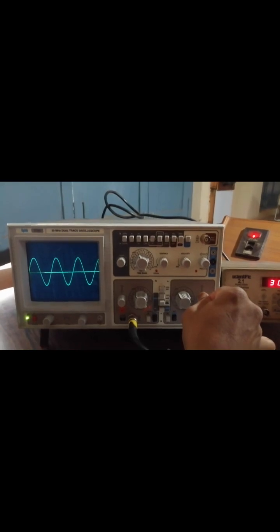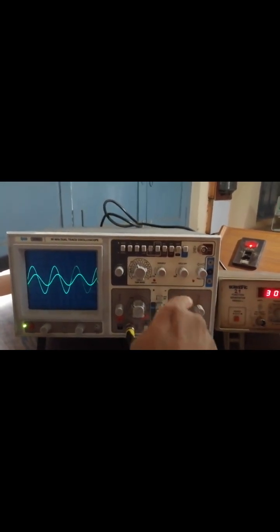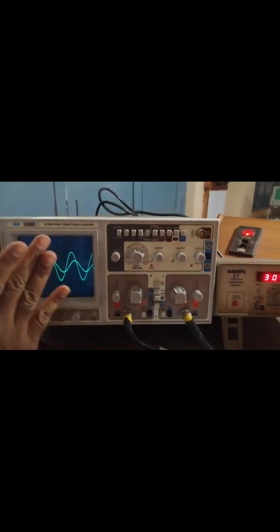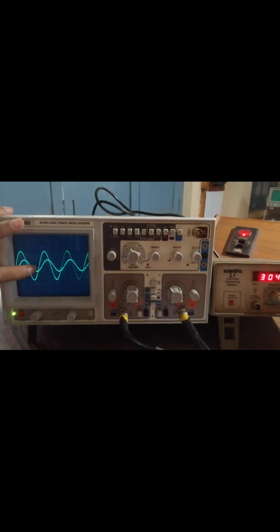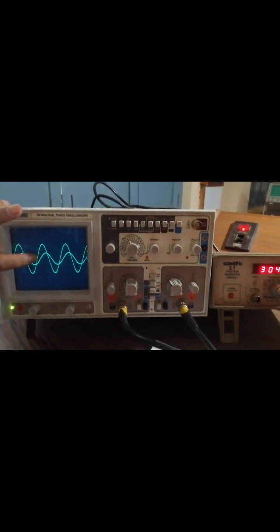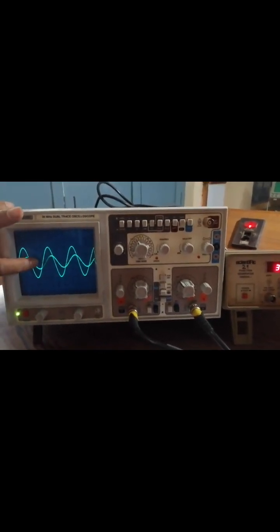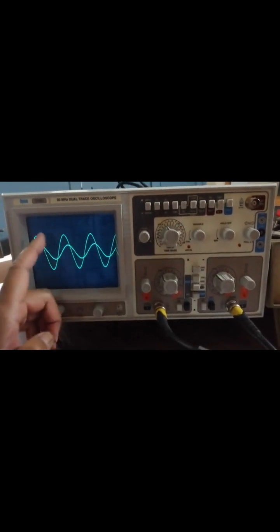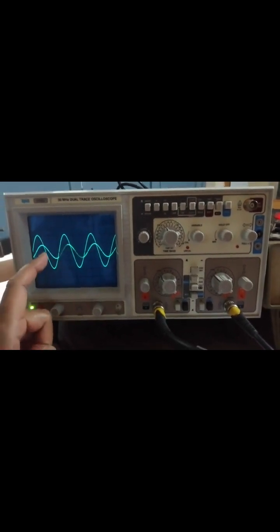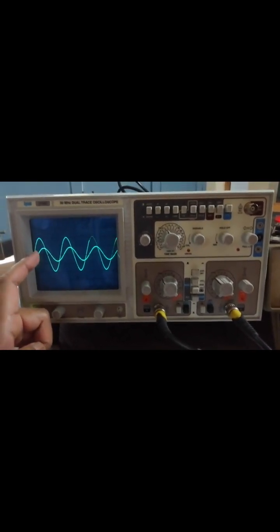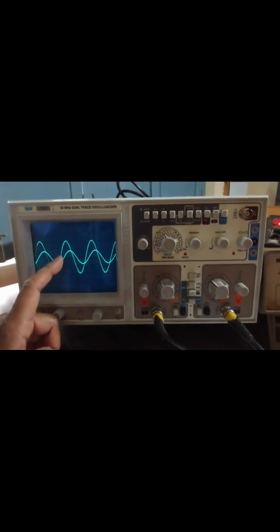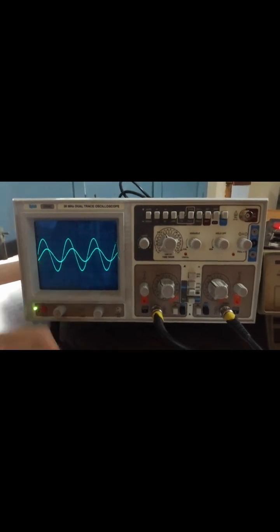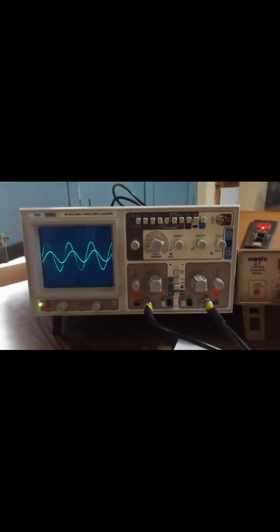I am activating the output channel and releasing the ground button. You are observing the output here. So it is basically a lag compensator. Lag means the starting point of the output should come after the starting point of the input. It is an indication that the output is lagging behind the input. So you need to consider the starting point, which comes first. Here input occurs first and then the output, so the output is lagging behind the input. In this context, we call this a lag compensator.